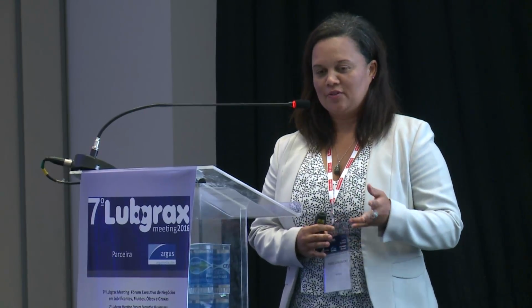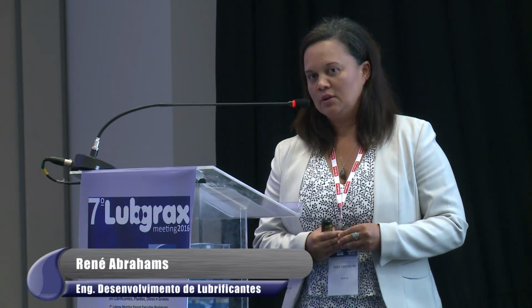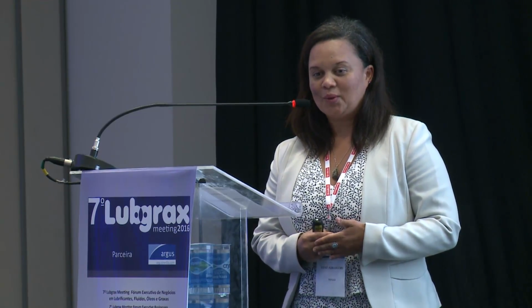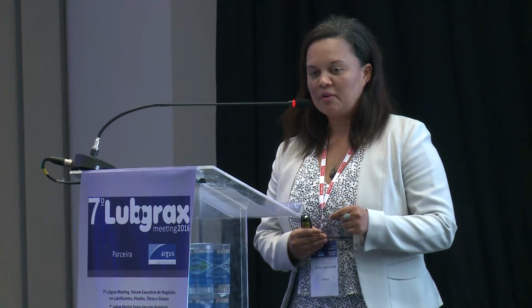Right, I wanted to highlight something that we discovered, quite interestingly: typically when one is formulating with paraffinic oils, you would include a pour point depressant, at least in those regions where it's required. So we wanted to understand how these new NYNAS products would respond to that. We used a very low dosage. On the extreme right, you can see the solvent neutral as a reference, and then the rest of the NYNAS products. And we see an excellent response to a pour point depressant, even at a very, very low dosage.